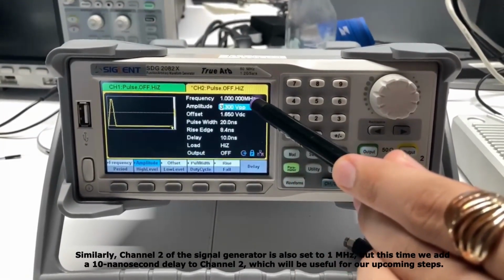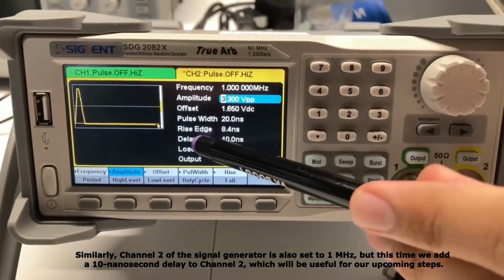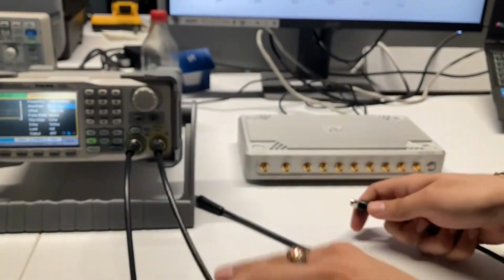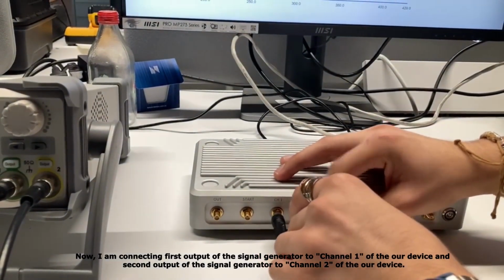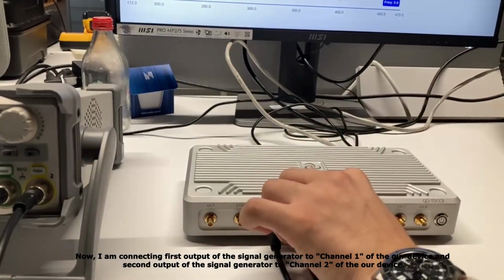Similarly, Channel 2 of the signal generator is also set to 1 MHz, but this time we add a 10 nanosecond delay to Channel 2, which will be useful for our upcoming steps. Now I am connecting the first output of the signal generator to Channel 1 of the device and the second output of the signal generator to Channel 2 of the device.